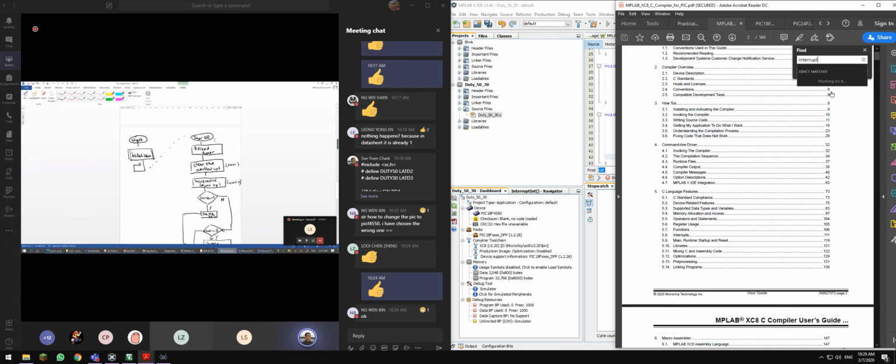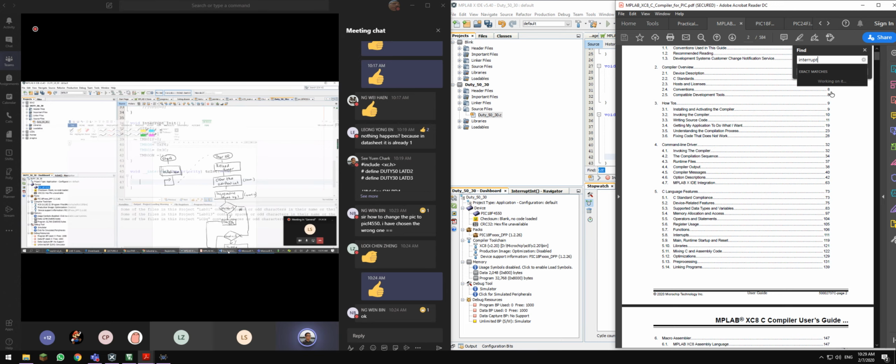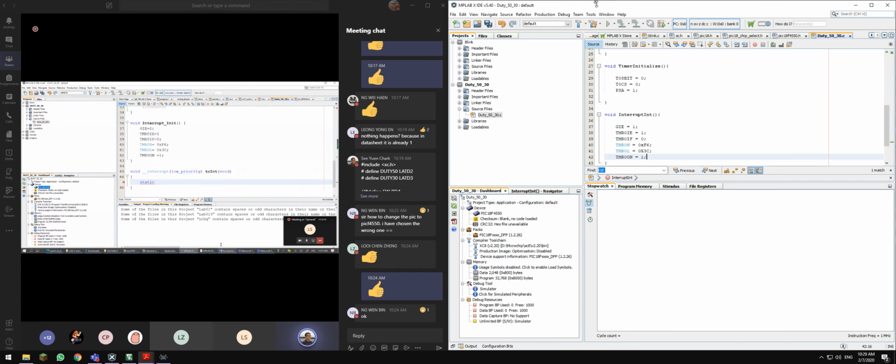So this is a timer interrupt service routine. The first thing you should do is reload your timer. We have a counter here, so we need to declare the counter. Remember, we use static because every time it's coming in, the counter will not be updated if we define count to be 0.